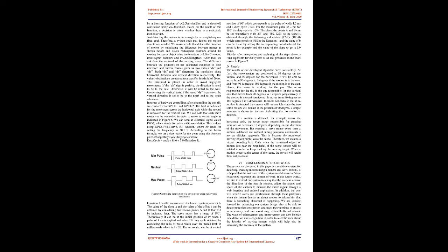Implementation summary. In our system, the mission was to build a functional system that detects motion, determines its direction and follows it using the Raspberry Pi, USB web camera, 2 servo motors, and a pan tilt bracket. The task starts by installing the necessary packages for the web camera and by checking if our USB web camera is detected by the Raspberry Pi by inspecting the dev directory. If a file named video0 exists, this implies that the web camera is successfully detected by the Raspberry Pi.